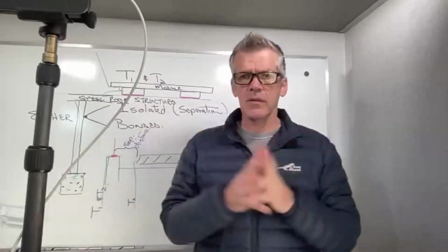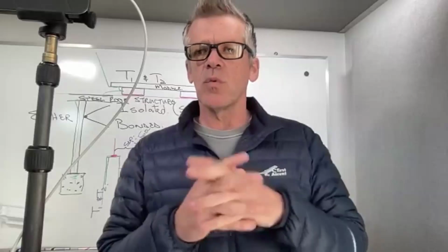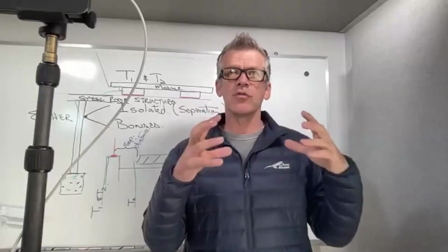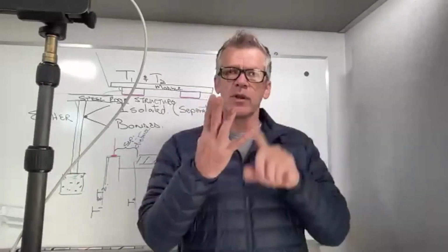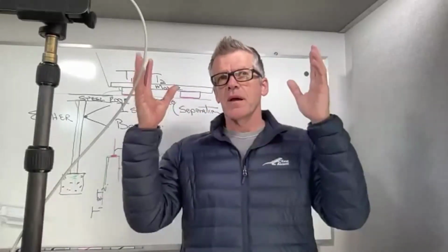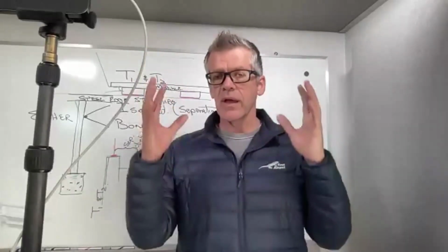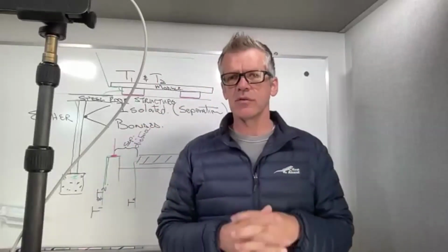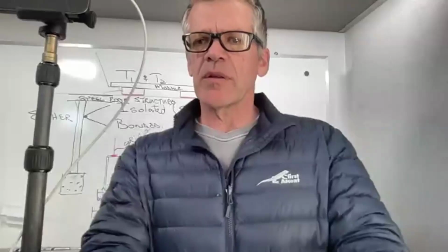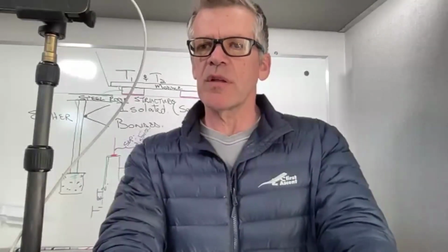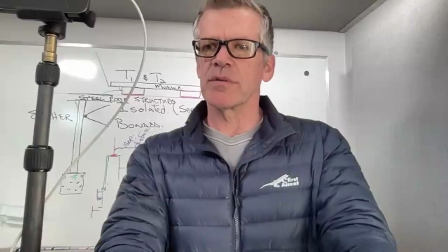So yeah, I think what you are referring to is where the blur in the industry comes in, because you've got to have a look: how many down conductors do you need? What is the kA of the lightning strike you're expecting? What is the material and mechanical and electrical conductive properties of the material that you're using? So it starts becoming difficult as far as calculations are concerned, but I'm sure you guys would be able to give Kenneth a call and he'd be able to chat you through that part of it.